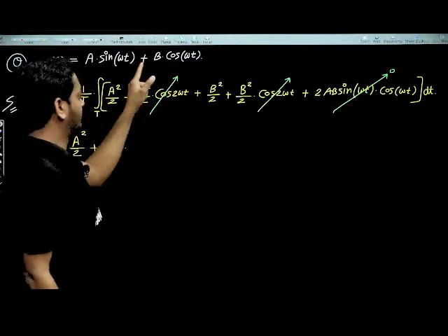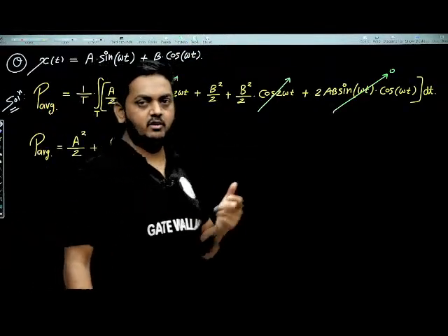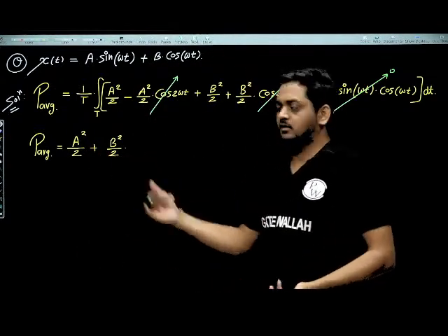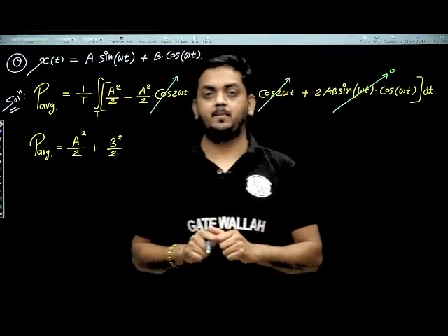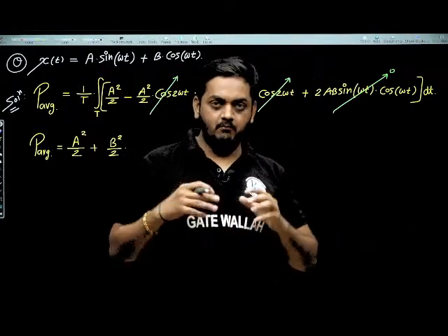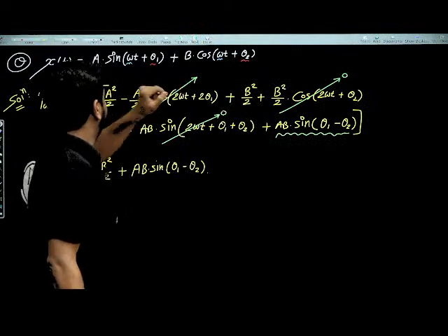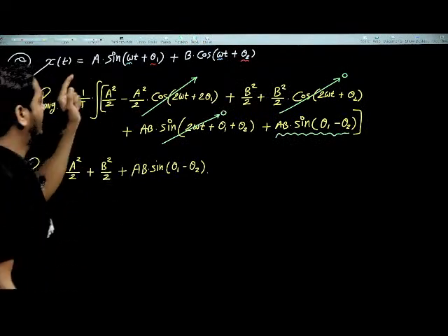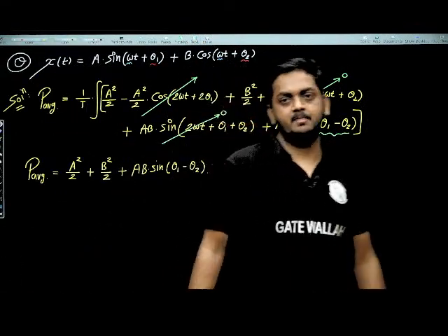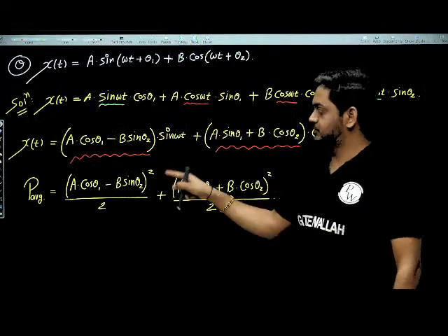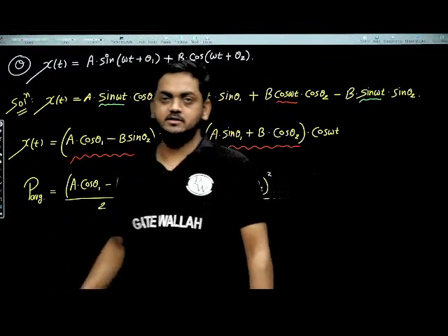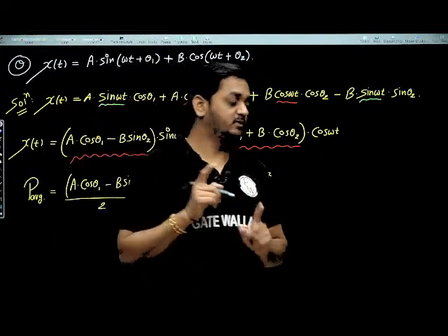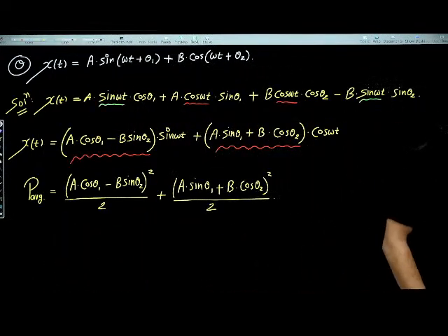If same frequency without additional phase angle, then also you can add the individual signal power. But if same frequency and additional phase angles are there, then simply follow this procedure. You cannot simply add individual signal power. This is a very crucial point. Is this clear?